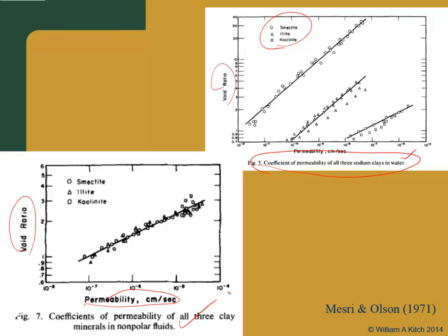Notice that if you had a bentonite, and let's pick one, a void ratio of 2, you thought you were going to get a hydraulic conductivity of 10 to the minus 11. Let's see, we come over here too. But it turns out your landfill is actually holding carbon tetrachloride instead of water.